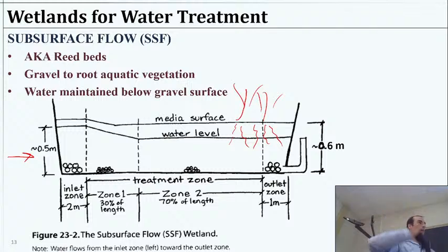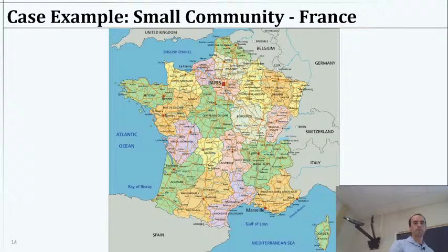That's going to pull a lot of air into the gravel, a natural suction motion pulling air in. So you'll have a fair bit of treatment. Some of that might go anoxic down towards the bottom, but that's not a terrible problem, and if you give it enough time, that's probably solved naturally.